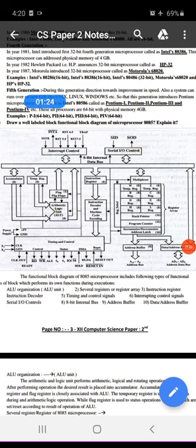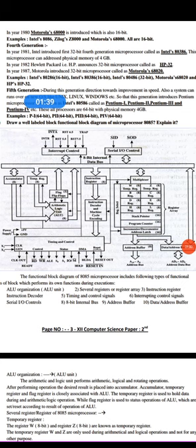The second part of 8085 is the register part. So you see a number of registers over here. The most important register is the accumulator, because whatever data we want to process is first brought into the accumulator and then it is passed to the ALU. So the accumulator is an important register. Why? Because before and after execution of an instruction, data is present in the accumulator. The accumulator of 8085 is 8-bit.